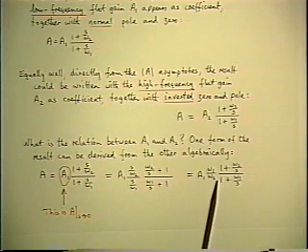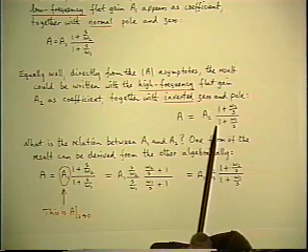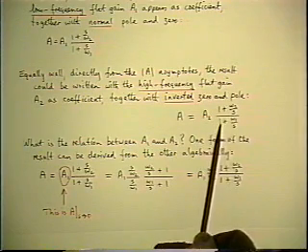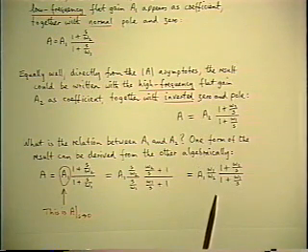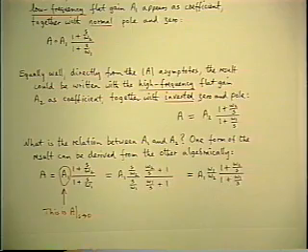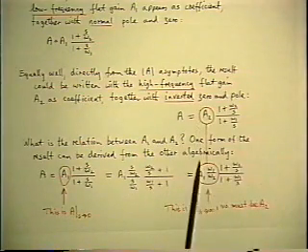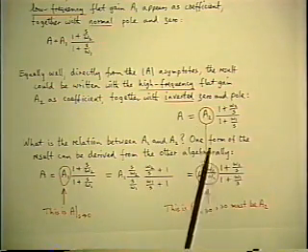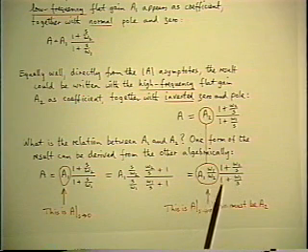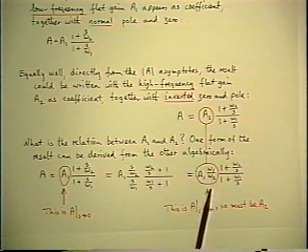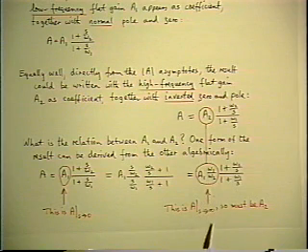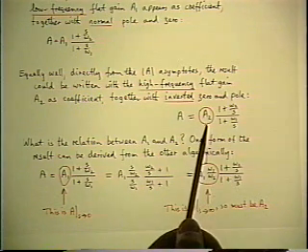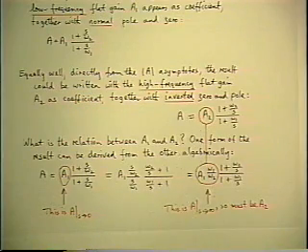And if you compare this algebraic result with the one that you would get by writing the same result by looking at the diagram, you see that there has to be an equivalence between these two flat gain coefficients. They have to be the same, which immediately gives you a relationship between the two flat gains in terms of the ratio of the two corner frequencies, omega 1 and omega 2. So the interpretation of this coefficient must be the gain as S goes to infinity, which is the definition of the A2.